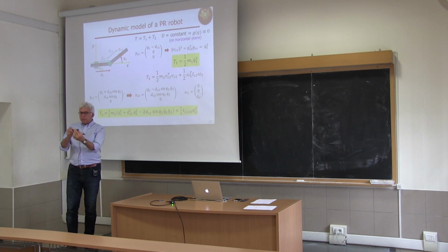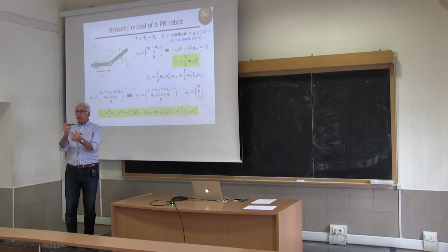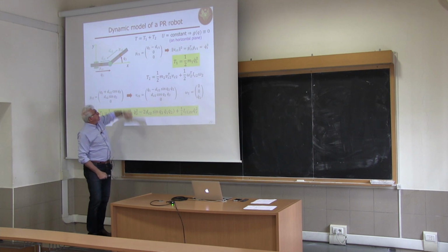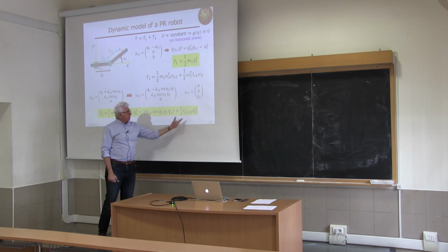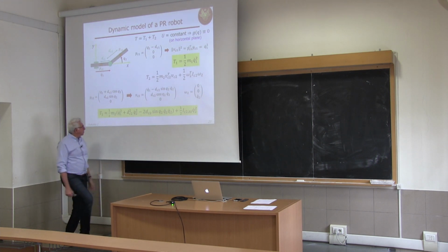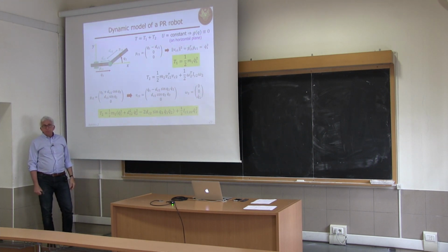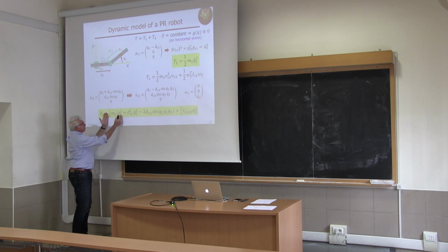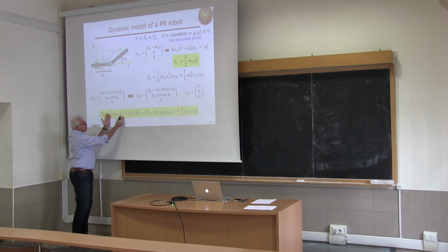So what matters is only the rotation of the last link. Pay attention, this is around its center of mass, so around the position PC2. And that's this contribution. This is because of the decomposition in the Koenig theorem. However, you can already realize that this part is only the kinetic energy of the first link.